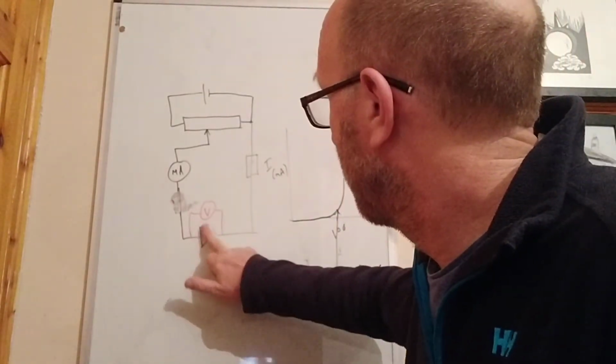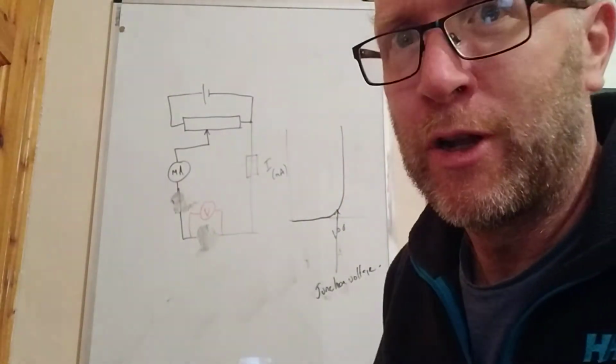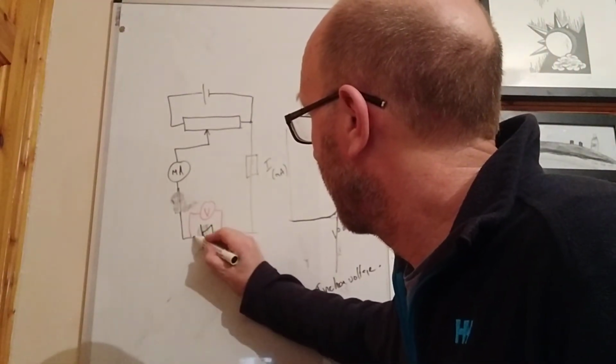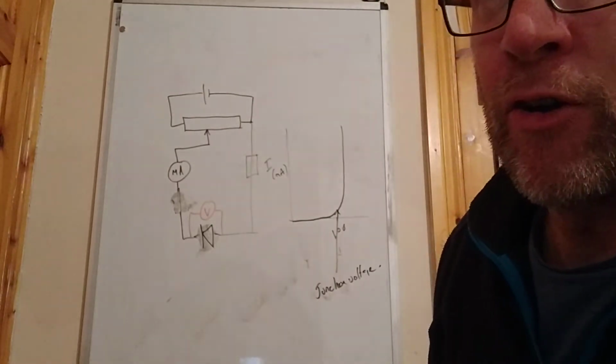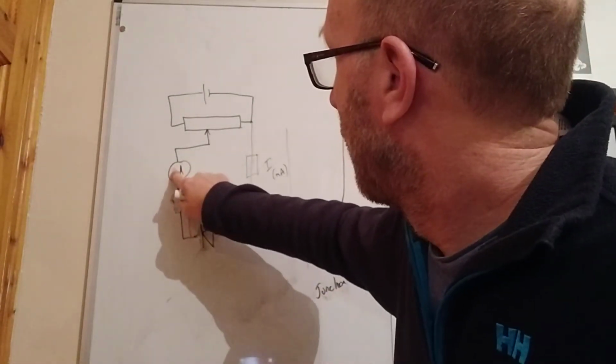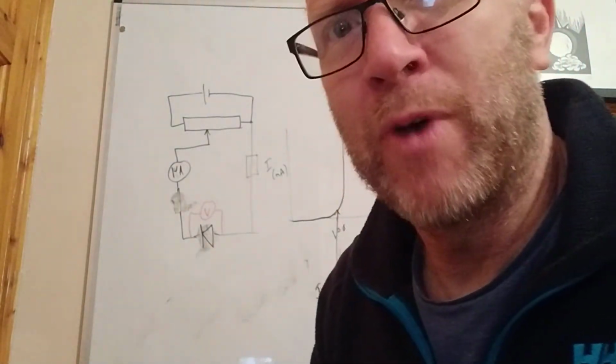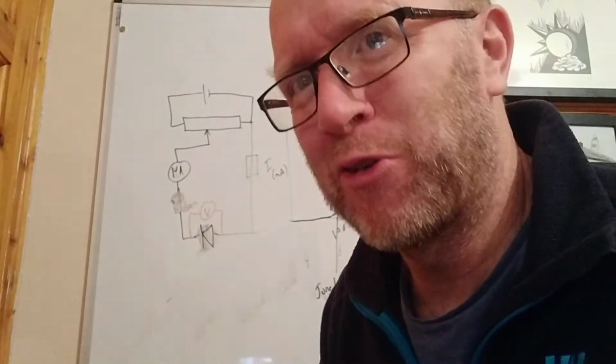Okay, if you reverse this, so changes you're making. You're reversing the direction of the diode. That's the first step. The current is going to be very small. So you replace the milliammeter with a microammeter. Second change. Third change is the real subtle one.